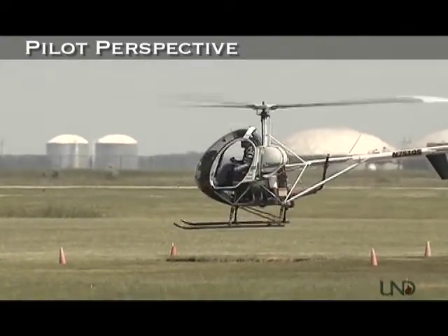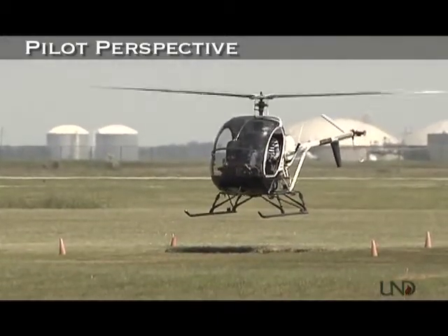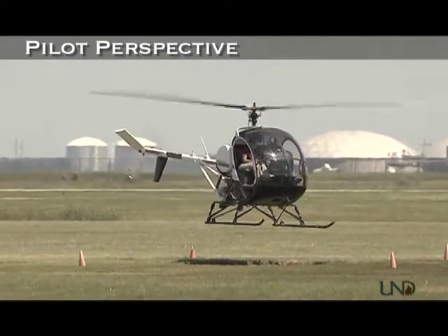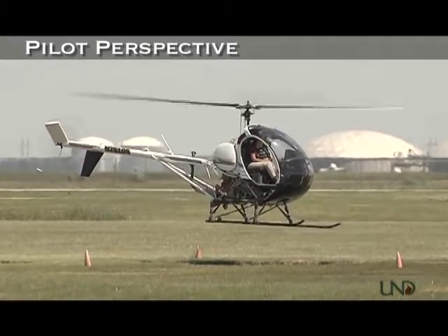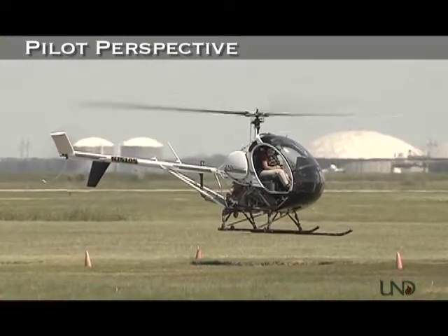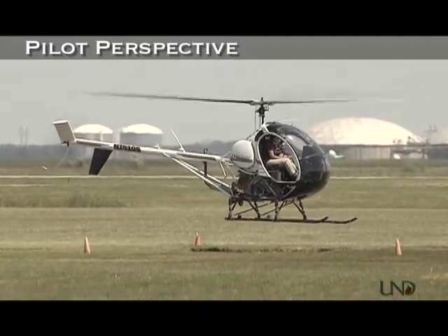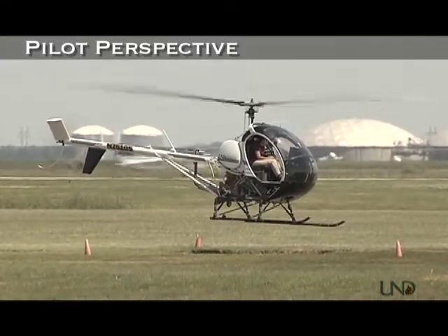Unfortunately, wherever you're taxiing, it's very rarely into the wind the whole way. If you have a crosswind, the nose of the aircraft would always want to point into the wind, so it makes it much more difficult for the pilot to control. With an air taxi, generally you're at a higher speed, so the aircraft is more streamlined and also operating more efficiently, but you still have to terminate the air taxi into the wind if possible.